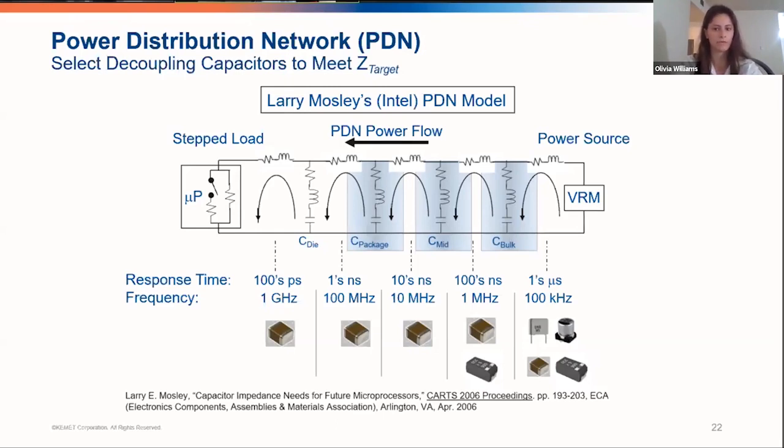So one common factor for all these decoupling capacitors: the lower the ESR and the ESL, the better the decoupling strategy will be, the more efficient it will be, the better it will perform. Typically, as we can see over here, a combination of ceramic and tantalum and even aluminum electrolytic polymers offer a good decoupling situation.